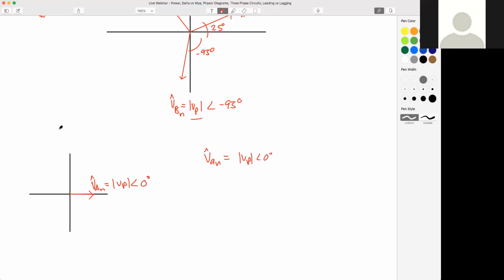For a positive ABC system that's balanced, balanced means all the phase values have the same magnitude and they're spaced apart by 120 degrees. ABC means the A phase value is going to cross the x-axis first, then the B, and then the C. So this is the direction of rotation, and this is the magnitudes and the evenly spaced out angles.